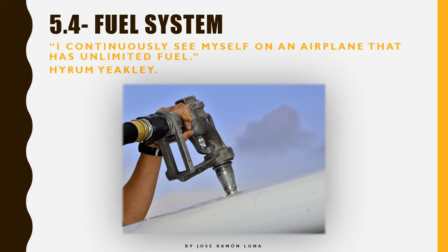We will observe that despite the small differences between the older and newer systems, the basic organization is pretty similar in the three of them, right? In the Cessna 172 November, the Cessna 172 Romeo, and the 172 SP. The differences and improvements basically come from the difference between a gas engine and a kerosene, commonly known as diesel, engine. They're different, so they're going to become more and more advanced, and they're going to bring improvements and differences. And also the difference between a carburetor engine and an injection one. That's going to bring some differences as well.